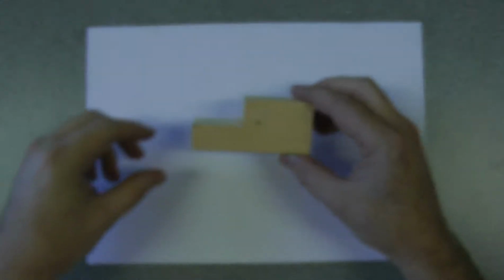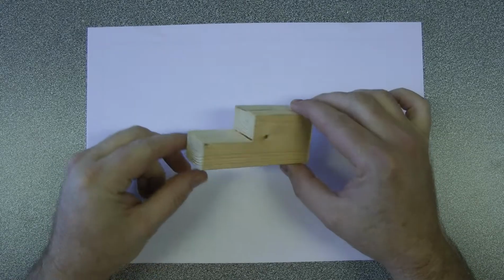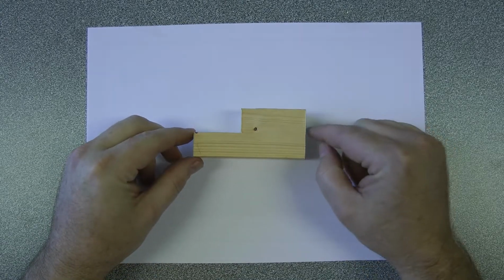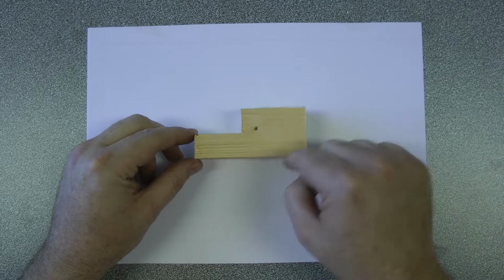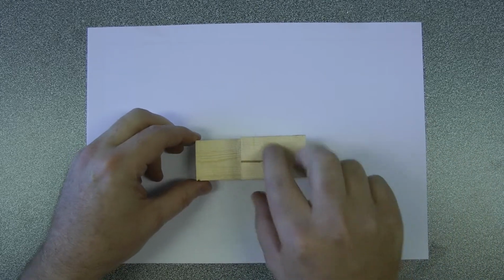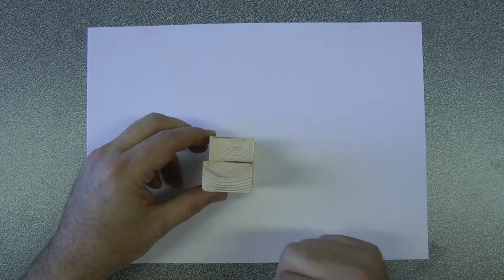This video is about how to do an orthogonal drawing of a shape, and we're going to be looking at this shape here. So this is going to be the front. An orthogonal view drawing, of course, are two-dimensional views, two-dimensional drawings of the front face, of the top face, and of a side face, in this case the left.